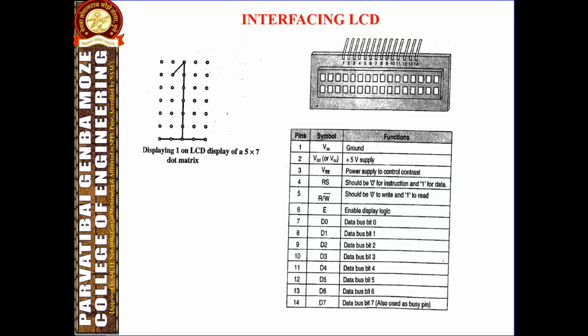LCDs generally use a common controller chip and common connector interface. Due to these factors, alphanumeric LCDs range in size from 8 to 80 characters. All the characters are interchangeable without any hardware or software change. They are arranged as 40 by 2, 20 by 4, 10 by 2, 20 by 1 or 20 by 2. The first figure represents the number of characters in each line. The second figure represents the number of lines the display has.